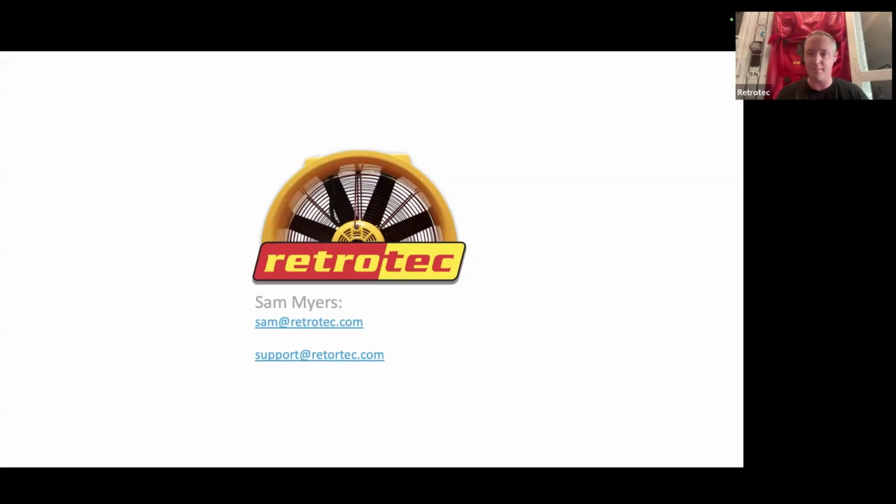A lot of them don't. They might run intermittently, so that's important to know: how is it going to be used? Otherwise, if it's used intermittently, you have to leave it as is. That can depend on manufacturer and installation. Some manufacturers have dampers built closed until it comes on. So that can really vary. One answer is not really going to apply to all ERVs and all installations.